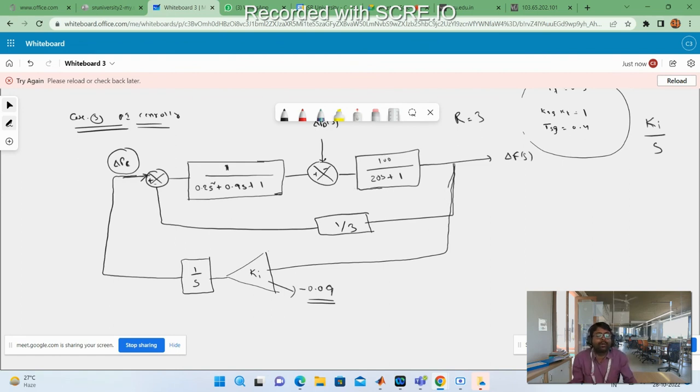Please tell me, friends, if I use a proportional integral controller to feed a signal to the speed changer based on the input coming from the frequency deviation, what is your expectation in the steady state frequency response of the power plant? Anyone? I will repeat once again. If I use a PI controller which takes the frequency deviation and sends the signal to the speed changer, your speed changer position will be updated.